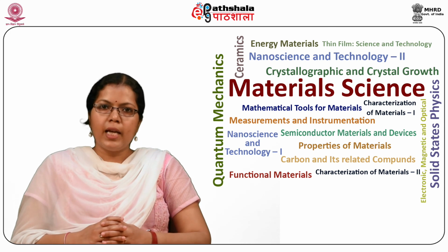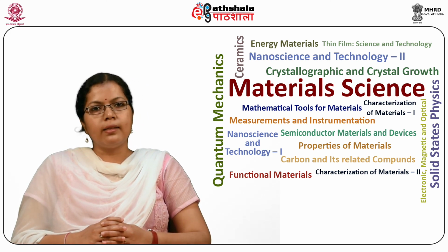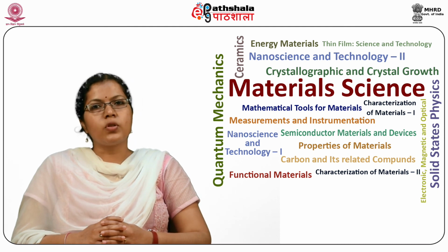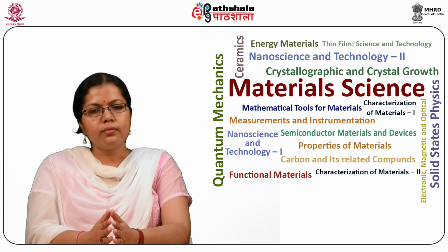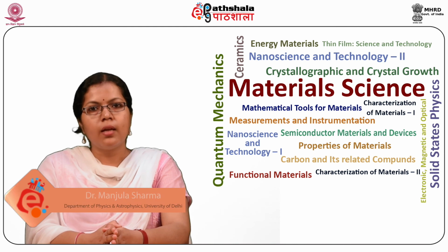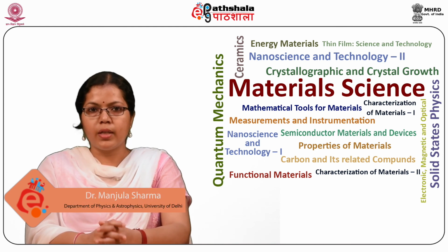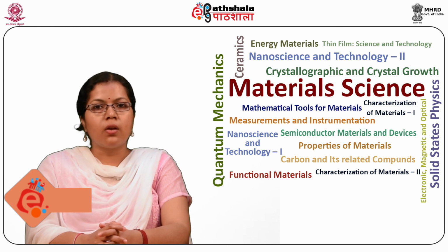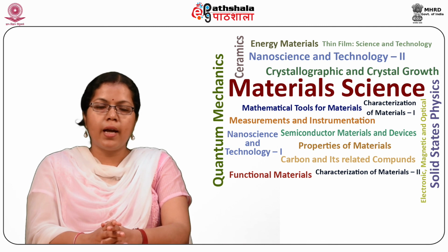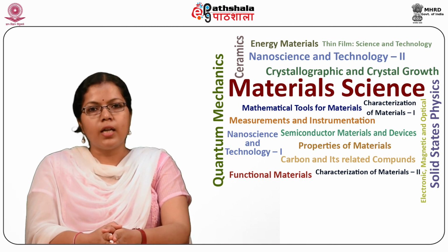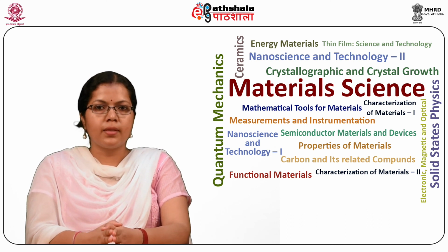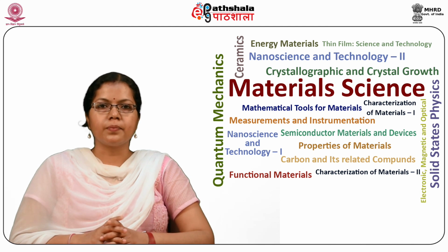So students, let us now summarize what we have learned in this module. In this module, we studied various types of optoelectronic devices. These devices are also known as photoelectric transducers. Here, we have covered the following topics: photoemissive cells, which are of three types: photocell, gas-filled photocell, and photomultiplier tubes. We also studied the photovoltaic cells and photojunctions, which are of two types, that is, the photodiode and phototransistor.